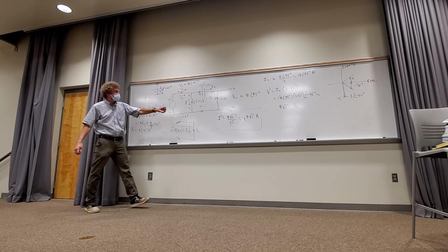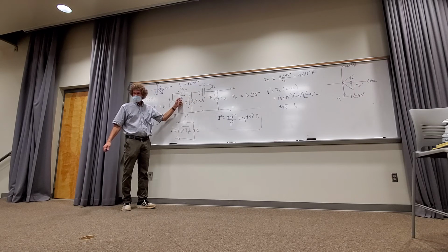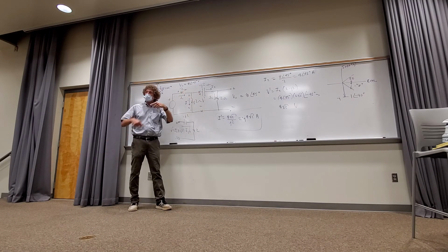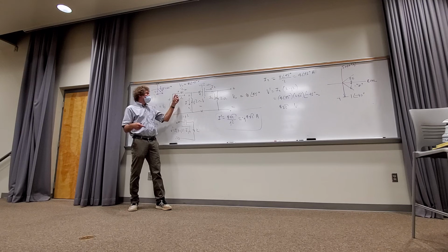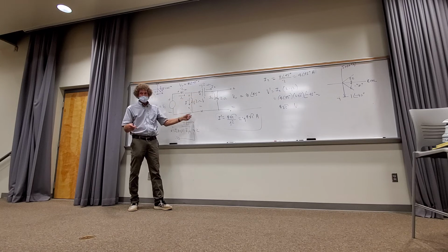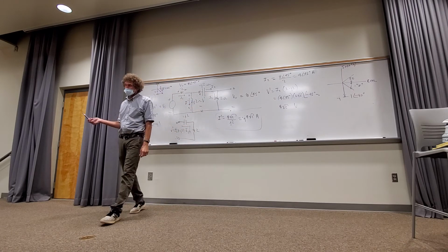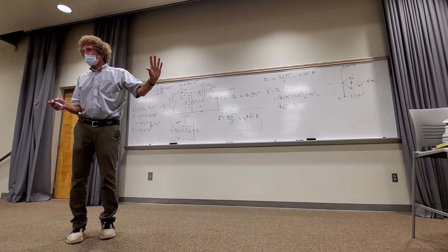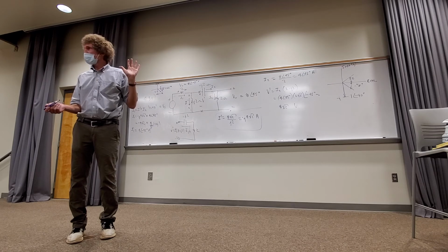Now she's right back there. This current would lead to this current right here. It would lead to it for one reason, because we could use current division. We could say this current times this impedance over this impedance plus this impedance would be equal to I2, and we could invert everything and get this current. But once we got that current, we still don't have this voltage. To get this voltage, we'd have to get this voltage here no matter what. Okay? Now technically, if you had that current, you could get the voltage here, and you have the voltage here by just multiplying I2 times that. But the way I did it was meant to show you how to get each and everything going in a reverse order of the usual way. Okay?